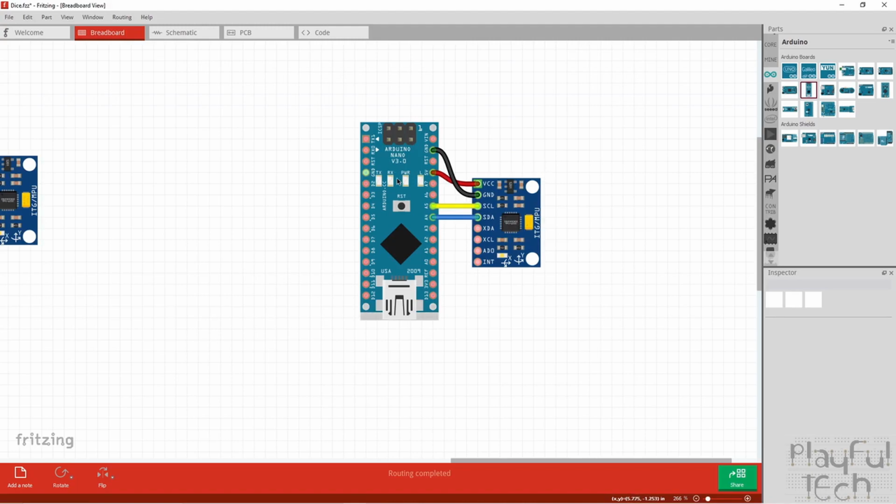So even though the Arduino is theoretically pulling them up to 5 volts, because those onboard resistors are so weak, they actually have negligible effect, and we can let the sensor board pull the I2C data lines up to 3.3 volts instead, and they're absolutely fine.